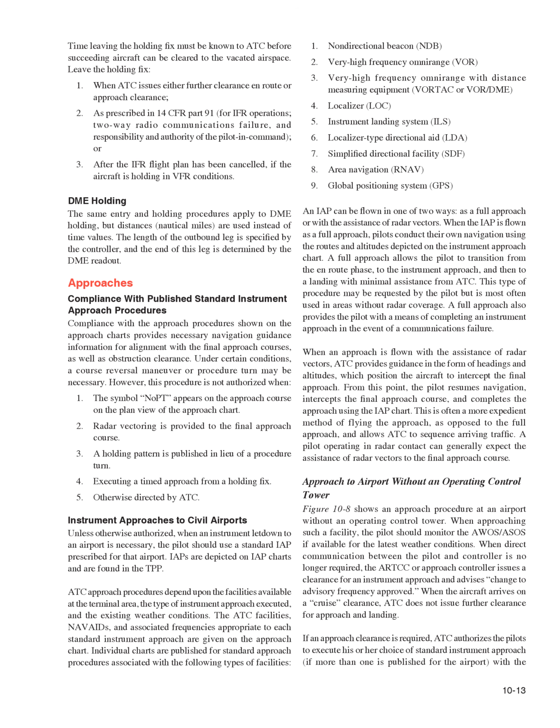Approaches. Compliance with published standard instrument approach procedures. Compliance with the approach procedures shown on the approach charts provides necessary navigation guidance information for alignment with the final approach courses, as well as obstruction clearance. Under certain conditions, a course reversal maneuver or procedure turn may be necessary.